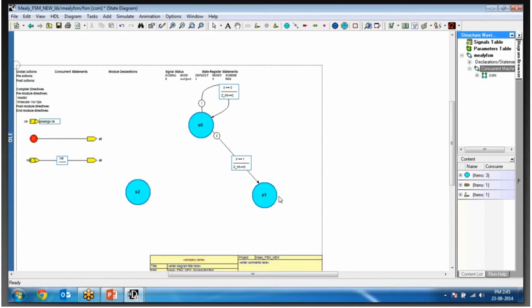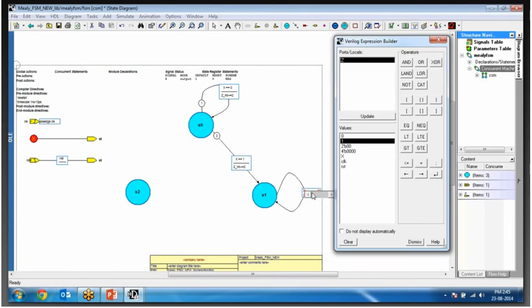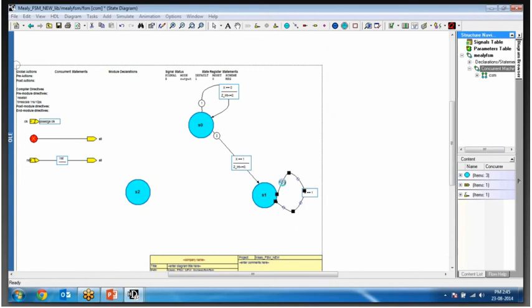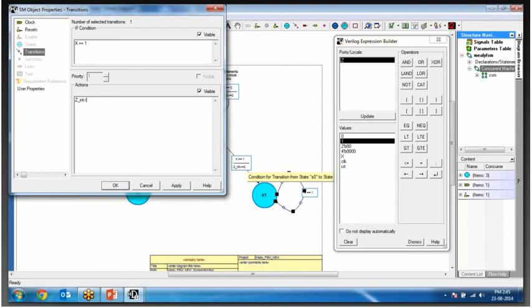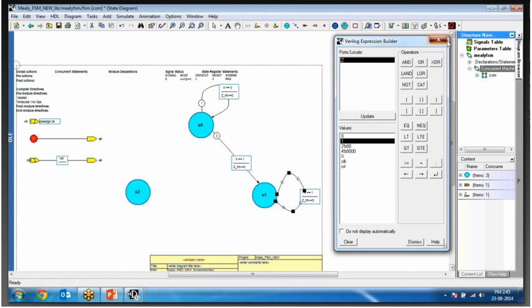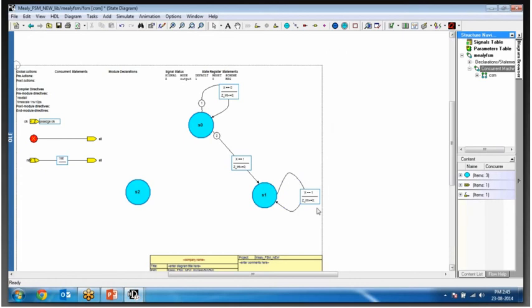Then we need a loop back to the current state, because what if we find the condition 1 again? So if x equals 1, remain in the same state. That is the condition I am giving. I will select the transition, and z_int should be given a value of 0. Now we have input and output both present in the arcs or transitions.